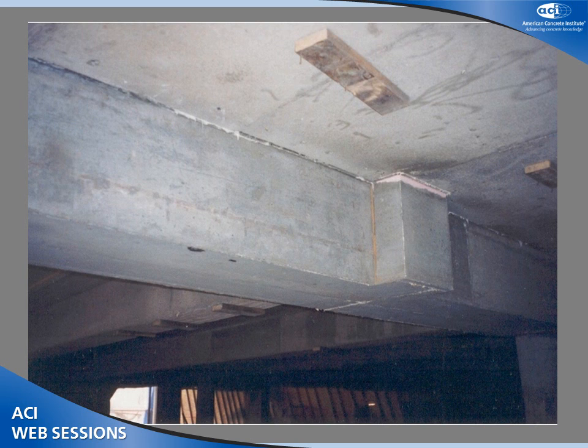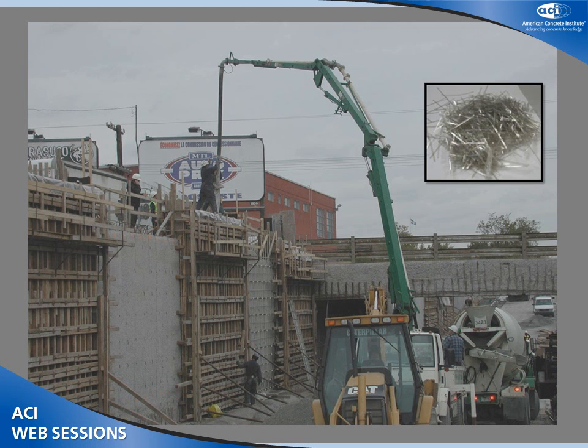So this was back in 1995, and in 1997 the Quebec DOT picked up this technology and developed a spec for the use of SCC, especially in repair applications, including some specifications for specialty cements, blended cements, and ternary cements for durability purposes. And in 2001, the city of Montreal picked this up after a few projects. And this is a project from 2003 where we were placing SCC for repair.